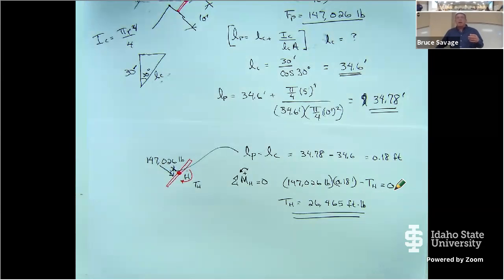We also have to look at what the scenario is when we start to open the gate and we start getting a dynamic situation. In a dynamic situation, we have fluid going around the top and fluid going around the bottom, and we can get negative pressures on one side than on the other side. So it's not as cut and dried as this simple equation for all conditions that may operate the gate.